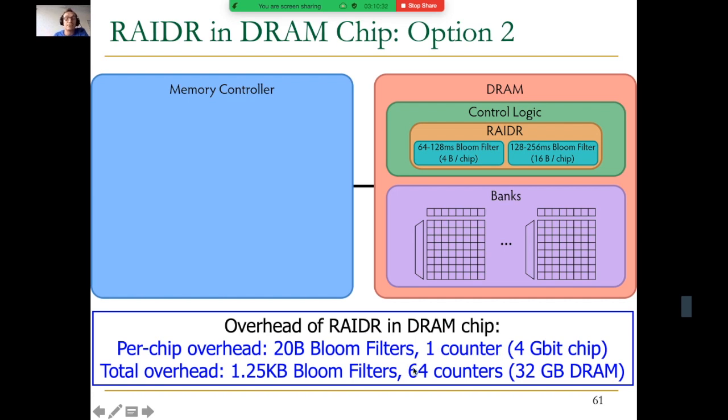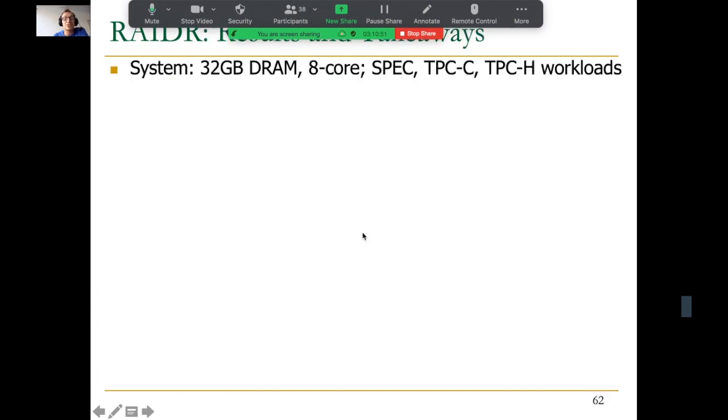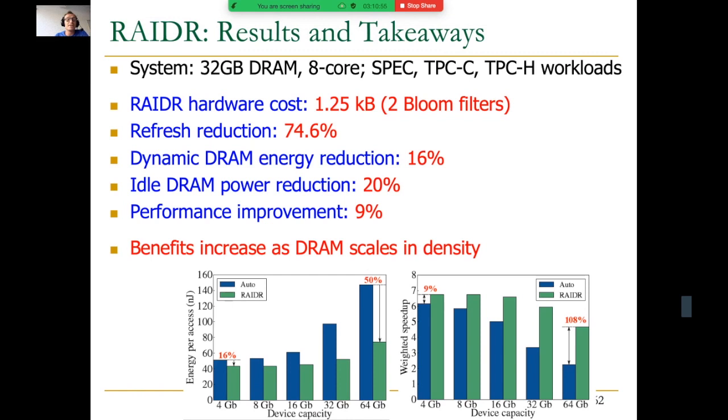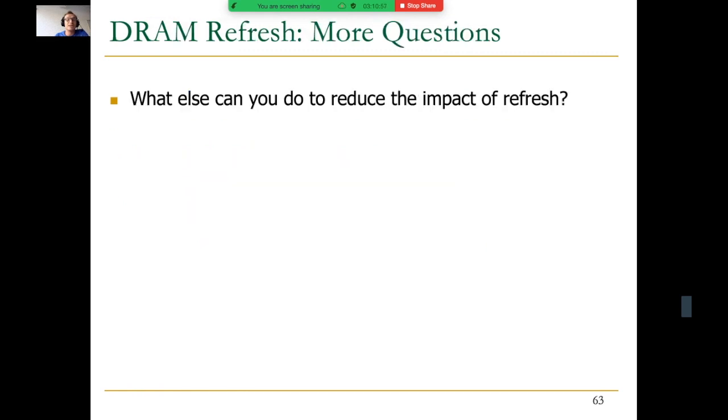You can see the overhead over here. But the benefits are very similar also. This way, you absolve the memory controller from issuing the refreshes at the right time, and maybe you can be more contained. But of course, the overhead is, it's easier to add logic into a memory controller compared to adding it into DRAM, because as we discussed, DRAM process is optimized for DRAM capacitors as opposed to SRAM logic. Okay, I've already given you, assuming you do all of this, you get significant benefits.